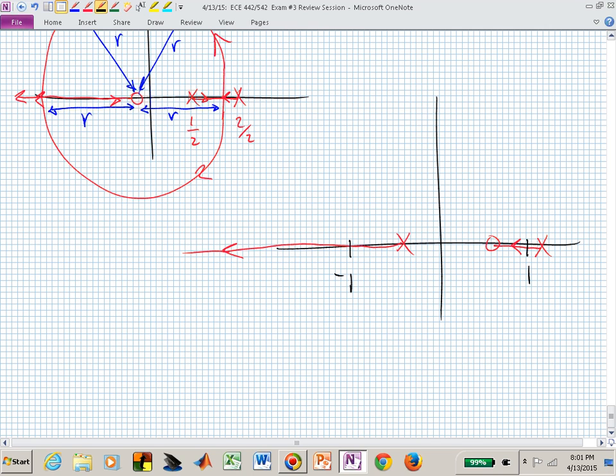What do you need to happen on the right for stability? You need to make that pole on the right get into the unit circle. So you need to crank up the gain to get you to 1, but what do you hope does not happen on the left? You hope that pole on the left doesn't zip out of the unit circle before the one on the right gets in. Is that clear?